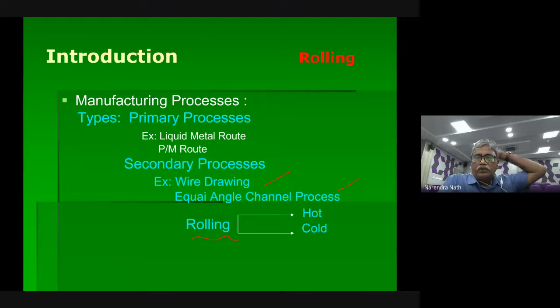In rolling, you can do it either at room temperature, or closer to the recrystallization temperature. It is not above, it is a little less. When you are doing it at room temperature without any heat, you cannot notice much metallurgical change. When you go for any process with temperature, you can see changes happening with respect to crystal growth, or even further metallurgical changes. When we say hot rolling, it is normally above the recrystallization temperature of that alloy. So that is the meaning of that. If I am using anything lower than that, I can still call it cold rolling. So with this, let us move on.